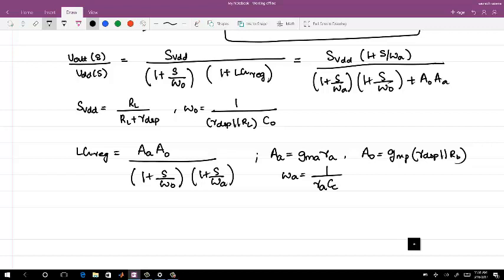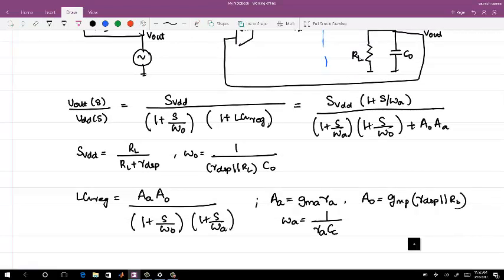The other one is a more simplified form which I showed. Now, the important part which you see here is that from supply noise to the output, you can see a zero depending on which pole dominates, or which pole location it dominates, right?